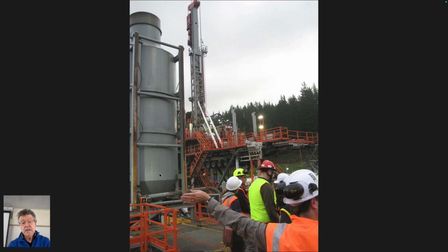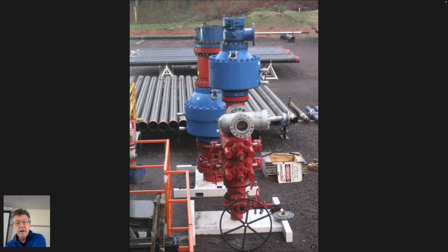Mixing tanks for mixing cement and for drilling mud to be able to support the pressure which is present here. People standing around. A blowout preventer, so the drill steel goes through this top, goes down into the ground, keeps on going, and this has the ability to shut off the wellhead if something goes wrong and you're going to get a blowout with very hot water coming out of it, or in oil and gas drilling, oil or natural gas coming out, which of course is an explosion risk.